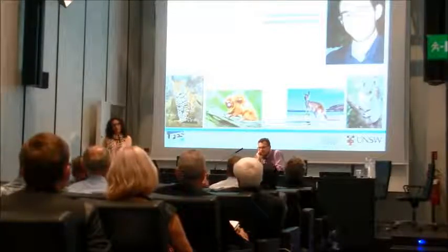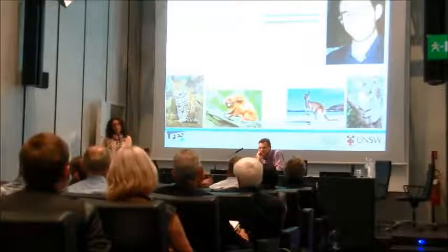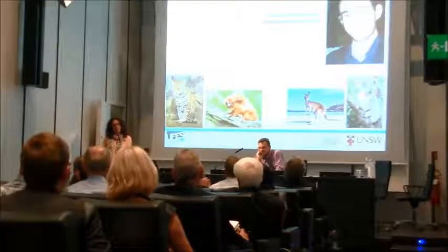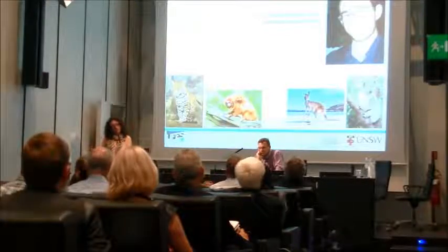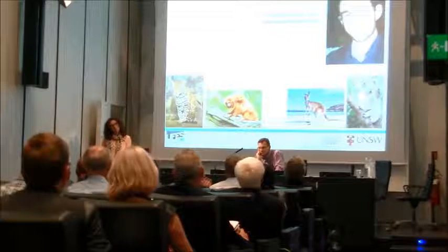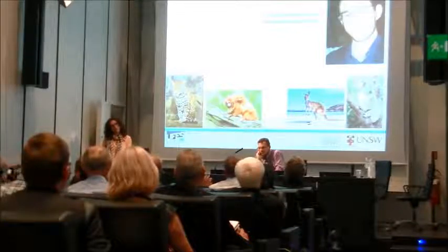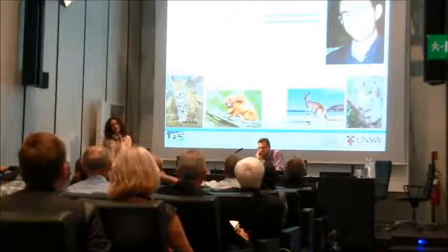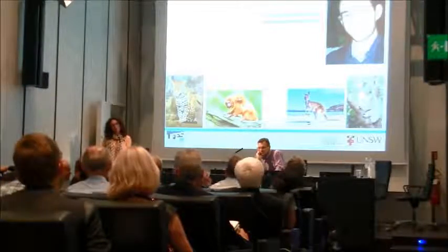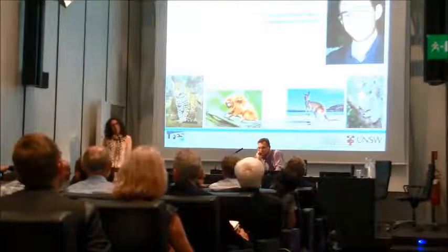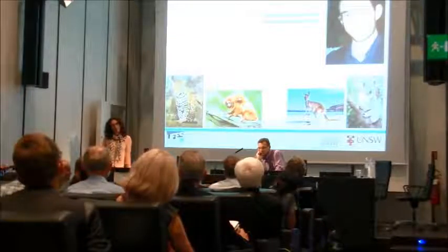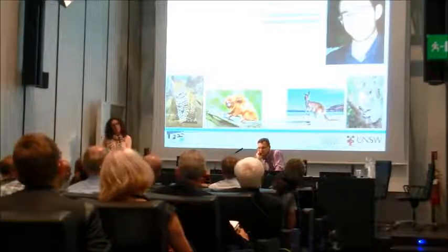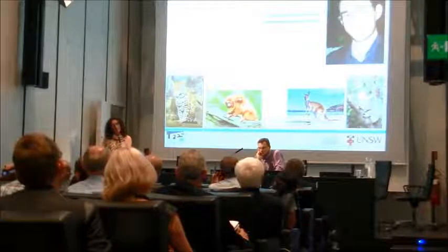And the second point is, if you look at atmospheric dispersion situations, the most important ones, by a factor of 20 to 40, are those with very low wind speeds, or even no wind. This gives the longest traveling distance. So we will never be able to measure true odor or true emission factor, but keep in mind these two facts.